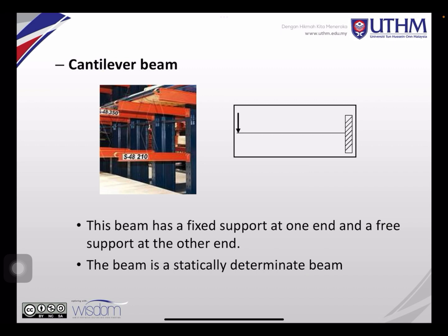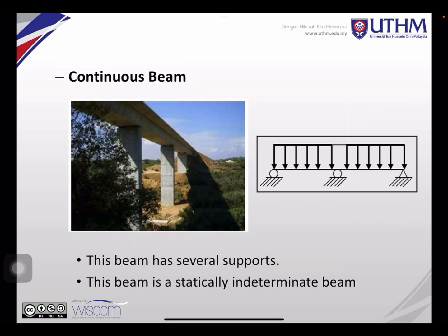So how about the cantilever beam? In a cantilever beam, you can see that the support is at this part, and then this is the free end. At the free end you will have a force here. This one you have a fixed support here. You have support reaction from here, and also the moment. So this is a statically determinate beam.